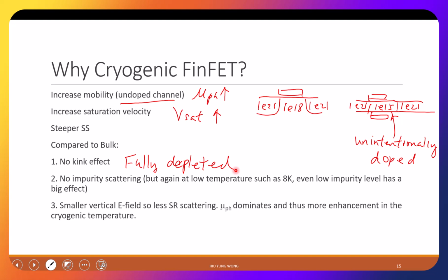So you're talking about SOI, right? Not the FinFET. For SOI, you can also dope it. Some people also dope it. Depends on the technology, really. But usually when it is thin, we try not to dope it. And then it depends on the thickness of the film. The film is going to change the threshold. So there are many factors. But if you try to ask me a question so that you know what technology you are using, then you better talk to the foundry.